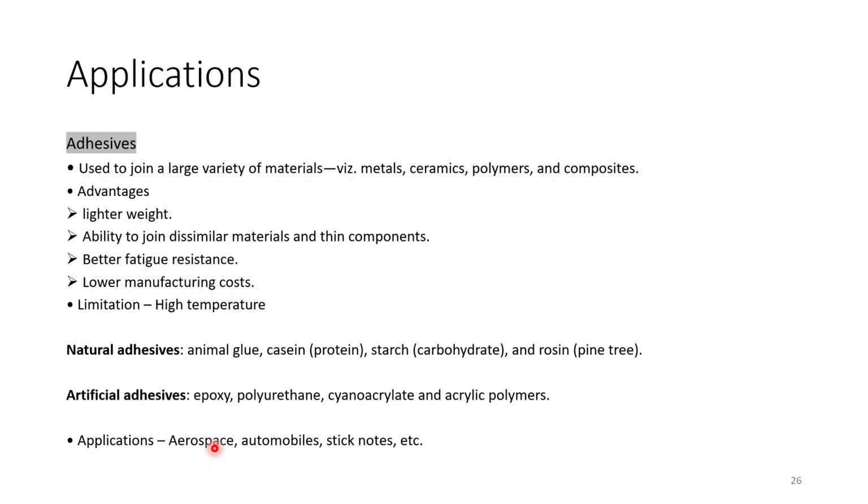One limitation is high temperature. These adhesives are polymeric in nature, so if you take the component to very high temperature, the adhesive will lose its integrity and the assembly is more likely to fall apart.